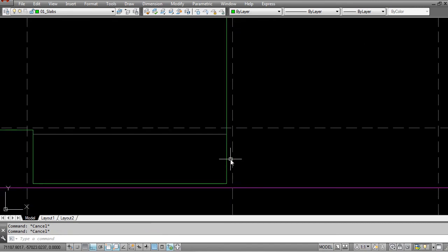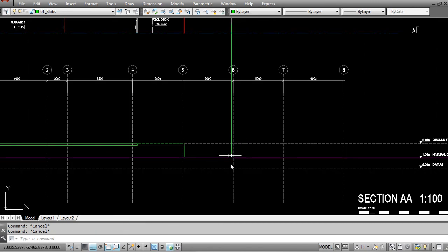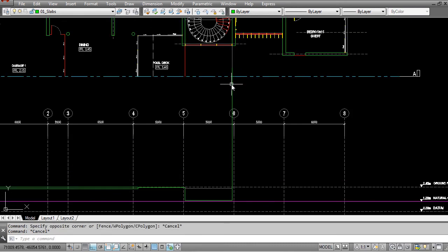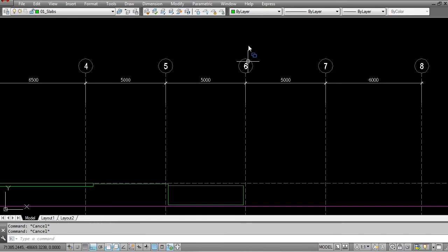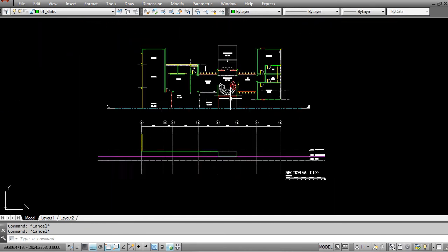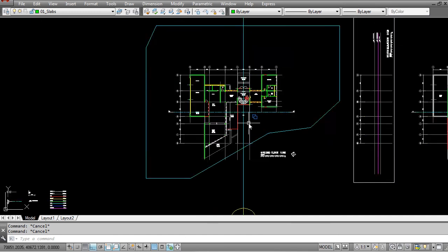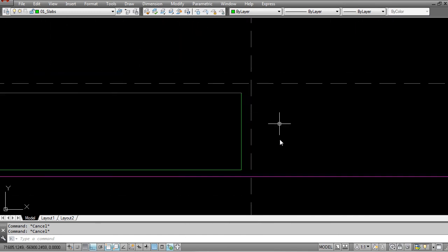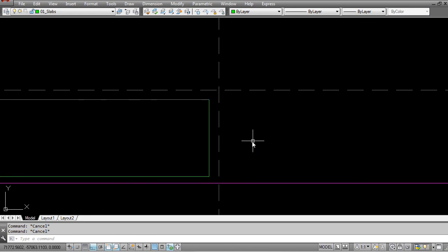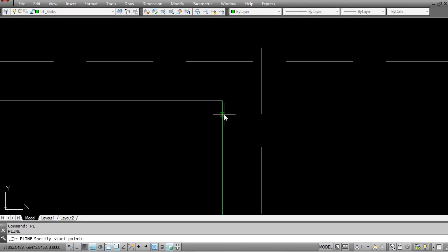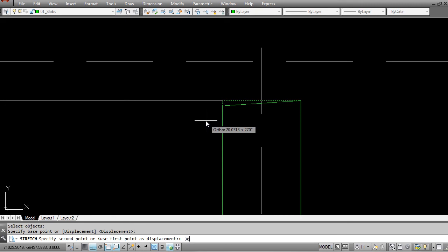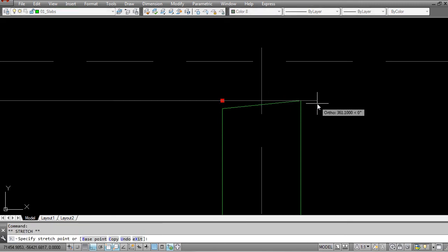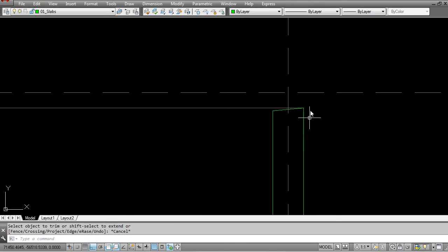And over here we're going to start drawing our water detail. So you can either do this now, it may be a little bit too detailed to really get into, especially since we haven't taken the time to draw it in plan yet. But I know from that sketch design from the original drawing that we have a rim flow situation. So I just know that I can draw in a default design for that rim flow edge, which looks something like this. If I just offset by 300, I'm going to draw a horizontal line, stretch this line down by about 30 millimeters. This line will extend all the way to that edge and get trimmed,